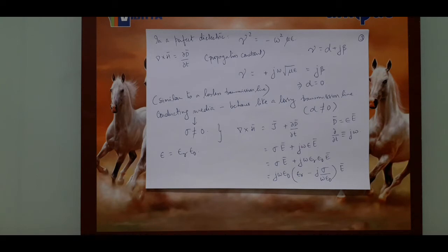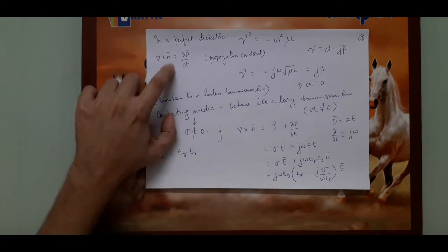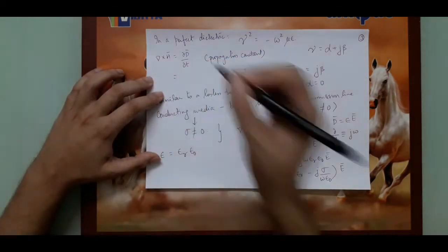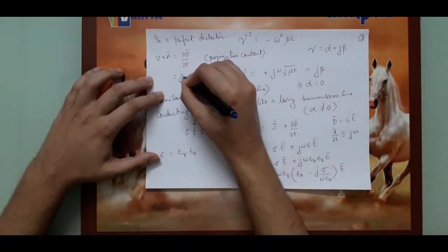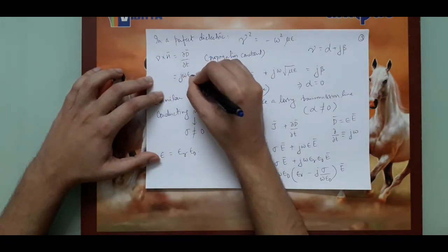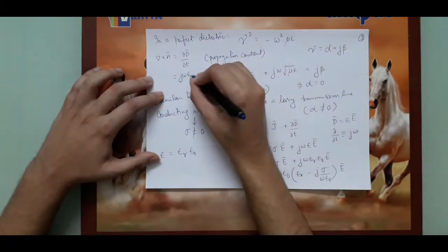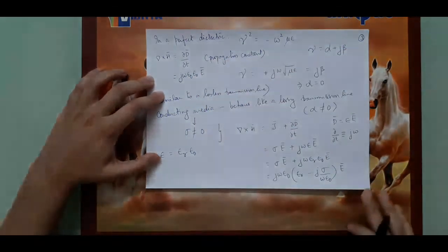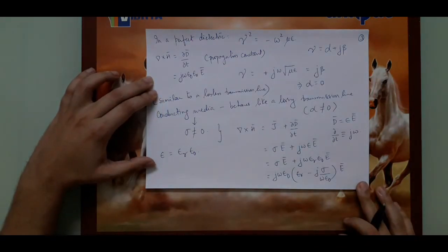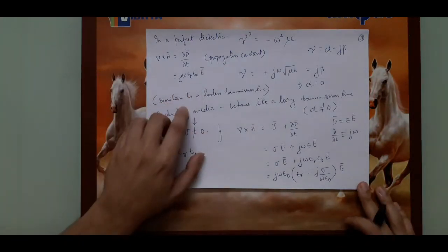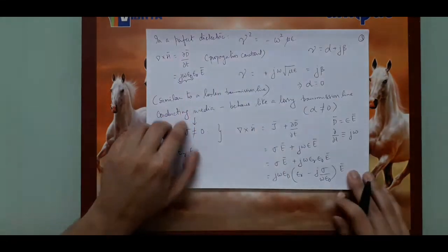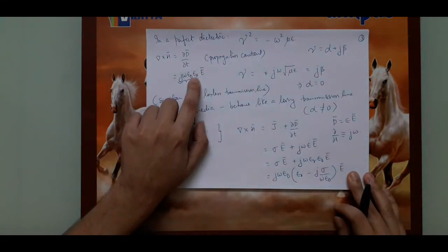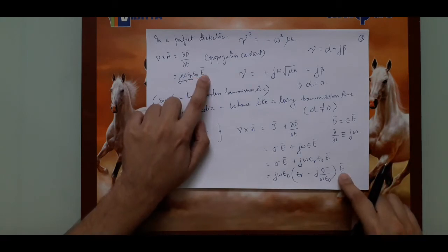So now this is what it looks like. Now compare this with respect to the perfect dielectric, where this was something of this kind, j omega epsilon 0 times epsilon r times E. So if you take the j omega epsilon 0 common, what you only have is the epsilon r over here and the E separated, which is over here.